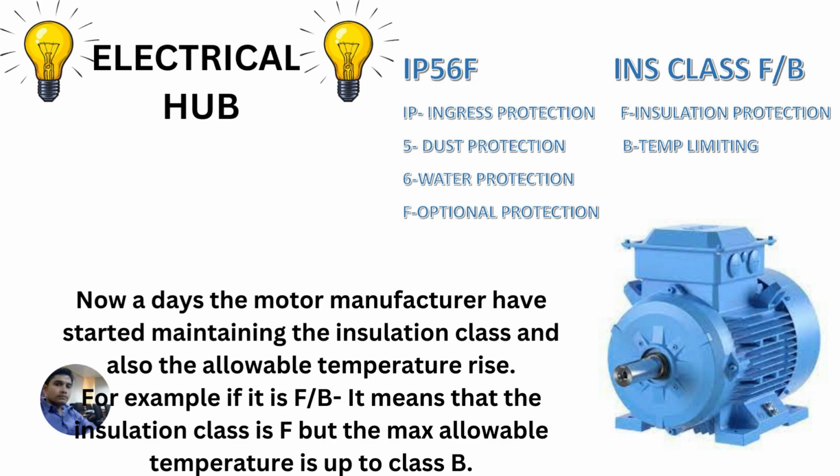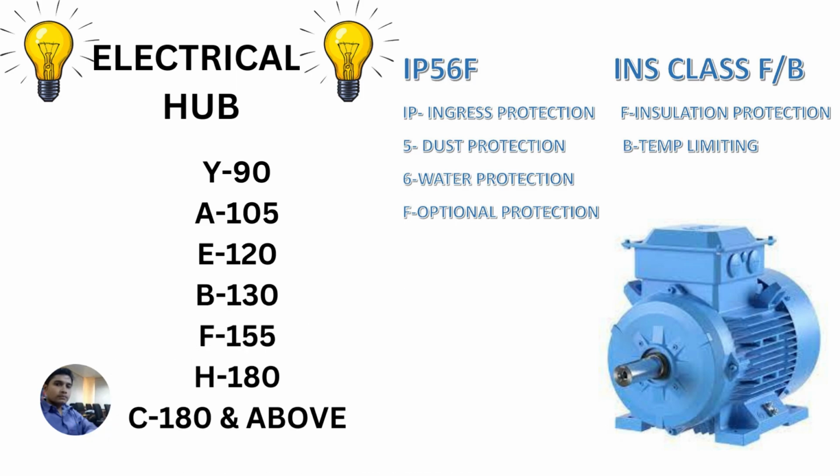It means that the insulation class of the motor is F, but to operate it in a healthy condition, it should not go beyond temperature class B. We will discuss what F and B are.